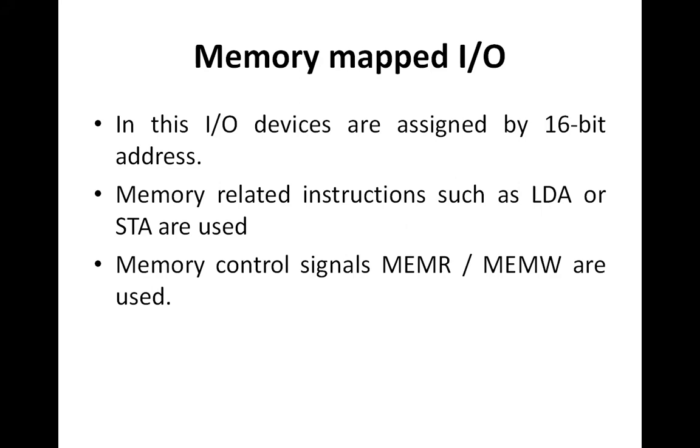As you know, the LDA instruction is load accumulator; it loads the content of memory into the accumulator. Similarly, STA is an instruction which stores the content of the accumulator into the memory. Similarly, LDA will be used to load the content of the input device into the accumulator, and STA will be used to store the content of the accumulator into the output device.